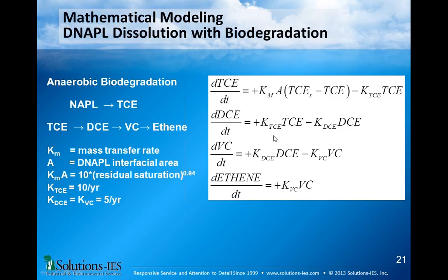And the thing I focus on is you're producing the acid right at the surface of the bacteria. So even if you measure the groundwater and the pH is 6, it certainly could be 5.5 or 5.0 at the surface, right where the bacteria are, because you're undoubtedly not measuring that in your monitoring wells.